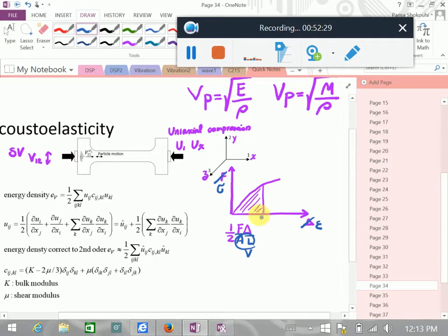So we can use this here. If this was linear, let's say we had K or E, however you like. The energy density would be 1/2 sigma epsilon, and then I would replace sigma by K epsilon. For reasons that I'll tell you in a second, I write it epsilon K. This is nothing else but sigma.